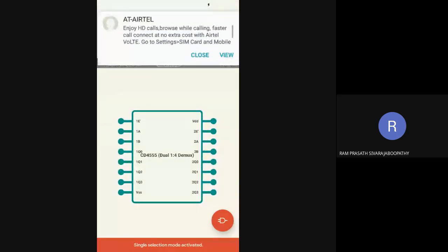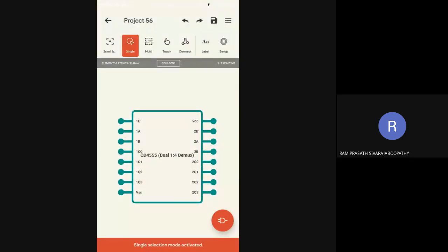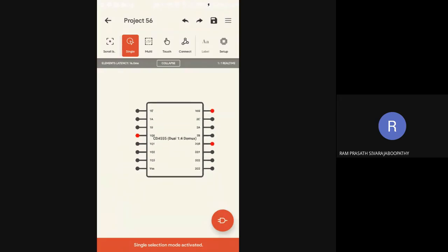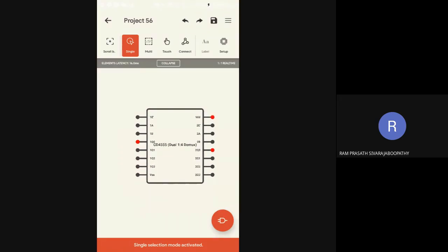Okay, here you can visualize. We are having a 1:4 demultiplexer, so I am going to use only the left hand side inputs. I have told you to configure this IC as a Demux. At the enable pin, 1 E bar, how did we say the data input must be given? Data input must be complemented and given.